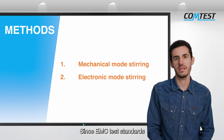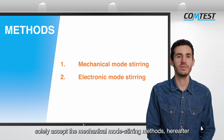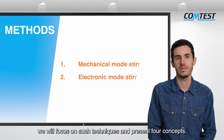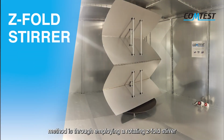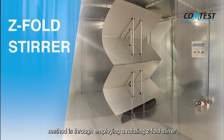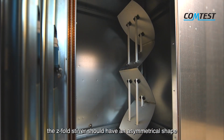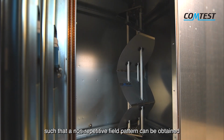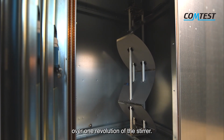Since EMC test standards solely accept the mechanical mode steering methods, hereafter we will focus on such techniques and present four concepts. The first and most common steering method is through employing a rotating Z-fold steerer. To provide a good chamber performance, the Z-fold steerer should have an asymmetrical shape, such that a non-repetitive field pattern can be obtained over one revolution of the steerer.